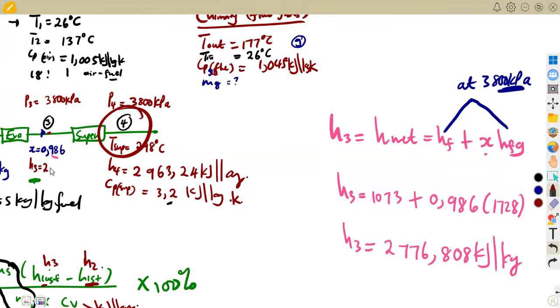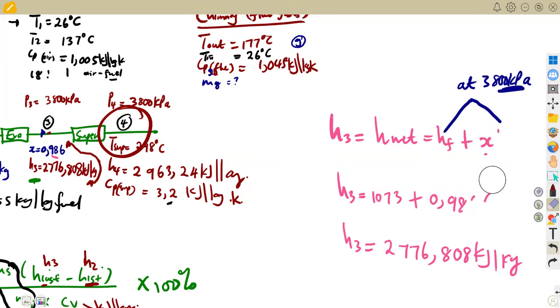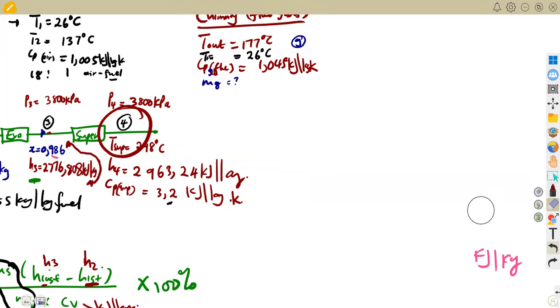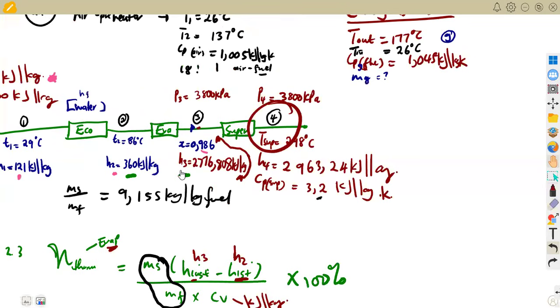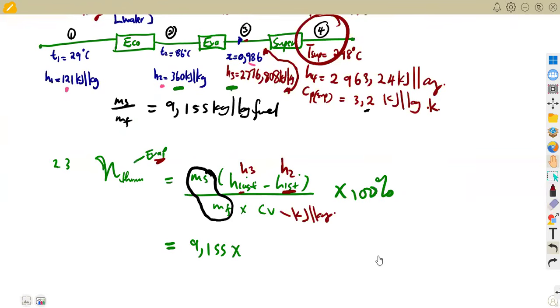You need these values. So instead of calculating them later, because you need them for that question, just calculate these values at once, provided that you know the information about the steam, whether it's wet or dry, everything you know about that. Use that as an advantage. You can calculate all the possible values from H1 up to H4 without a person asking you to calculate this. Then after that, you just have to fill in.